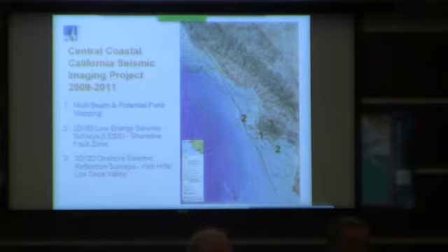and it also started investigations at the southern end where the shoreline fault goes into San Luis Bay. So this is to better understand the geometry of that intersection between these two major fault zones, as well as what's the overall length of the shoreline fault zone. Just to step back a minute, this is the trace of the Hosgri fault zone that runs along the edge of the continental shelf, and this is the fault zone that's considered to be the principal seismic source for our calculations. In addition to working offshore, we also decided to initiate a fairly comprehensive program onshore, looking at, again, the geology of faulting onshore, the Los Osos Fault, which runs along the eastern side of the Irish Hills, as well as other faults within the core of the hills themselves.